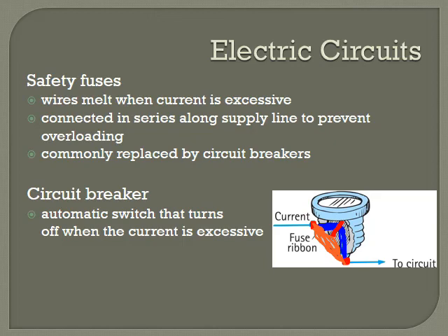So therefore circuit breakers were invented. And the nice part about a circuit breaker is that it is reusable. What happens when you run too much current through your circuit, it's going to flip the switch. That switch can be reset. Of course, if you continue to make the same demands of the circuit, it's going to flip over and over and over again. So hopefully you make corrections for whatever the problem is. If you're drawing too much current, if you're trying to run too many things at the same time, you just don't do that, and you won't have the circuit tripping all the time.